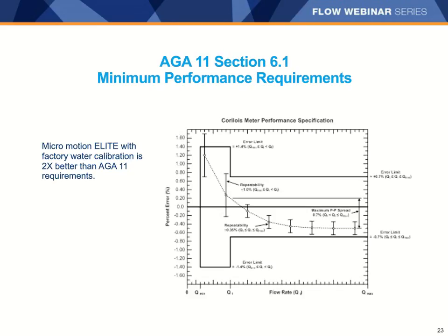At the same time, however, I can share with you that some customers have achieved agreement on the order of plus or minus 0.1% between the meter and the laboratory reference standards after applying the optional PWL adjustment. The traceability uncertainty of the meter measurement can never be better than the uncertainty of the reference standard that's used to calibrate it, so we recommend paying close attention to the uncertainty statements of third-party gas labs as you consider your options for calibration.